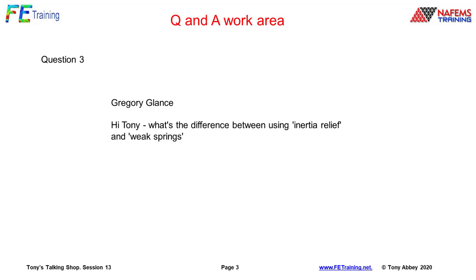I want to avoid rigid body motion. So like putting the scuba tank on a mattress, then the scuba tank can be pressurized. The mattress distributes those reaction points. It can work. It's often used as a system fix-up. I don't like it because it can introduce load paths through the weak springs, which do strange things, and it doesn't really get rid of rigid body motion. So it's not a technique I actually like to do.